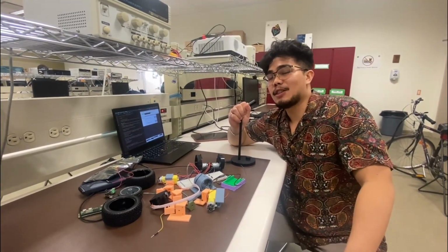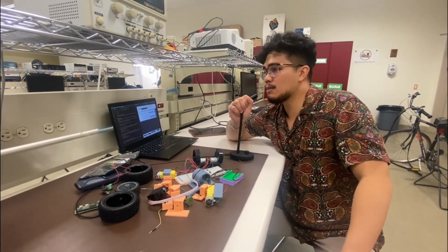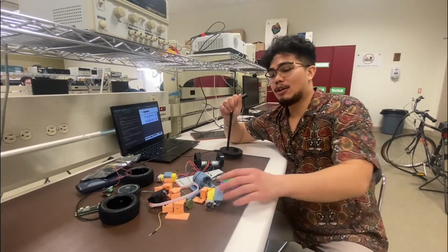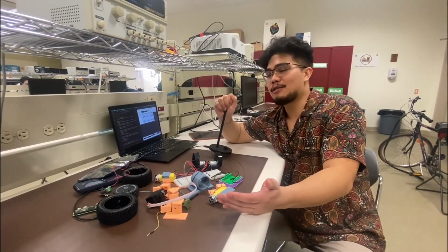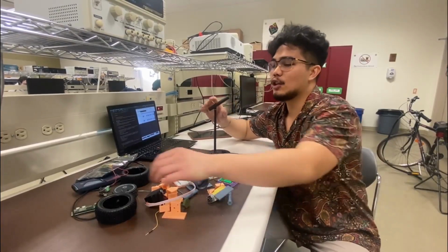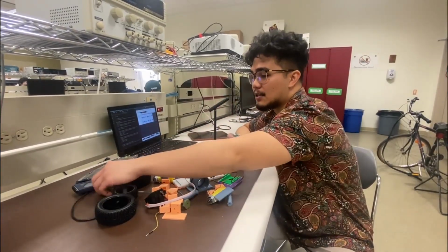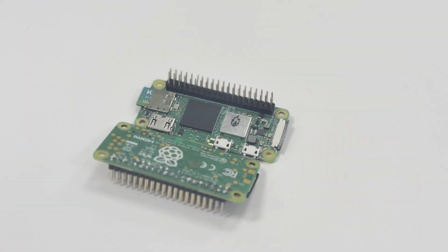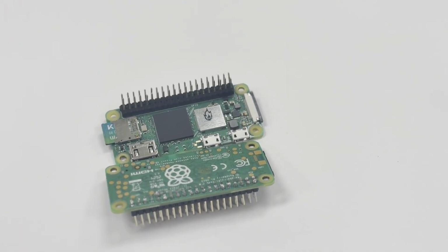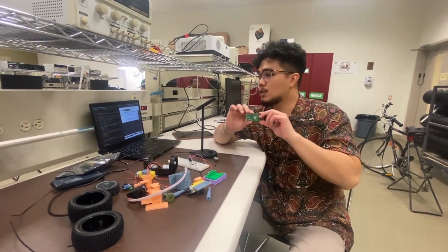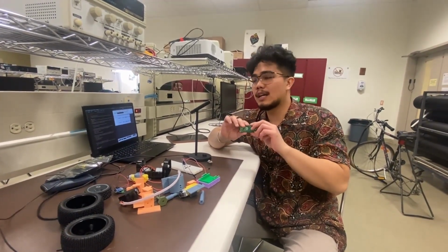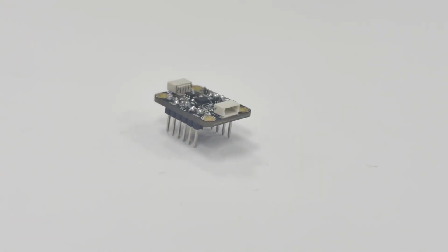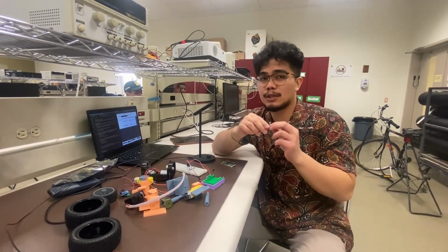Cypher was designed as a low-cost, real-time robotics platform for learning control systems. Our main goal? Create a modular, battery-powered robot that can balance on its own using only a few sensors and smart software. At its core is a Raspberry Pi Zero 2W running our PID controller, tuned using real-time sensor feedback from a filtered 9-axis IMU using a Madgwick filter.